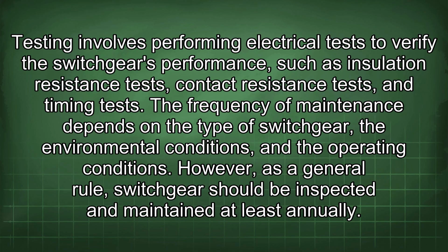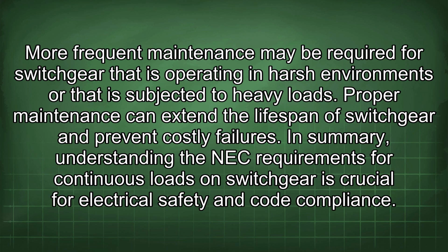Testing involves performing electrical tests to verify the switchgear's performance, such as insulation resistance tests, contact resistance tests, and timing tests. The frequency of maintenance depends on the type of switchgear, the environmental conditions, and the operating conditions. However, as a general rule, switchgear should be inspected and maintained at least annually. More frequent maintenance may be required for switchgear that is operating in harsh environments or that is subjected to heavy loads. Proper maintenance can extend the lifespan of switchgear and prevent costly failures.